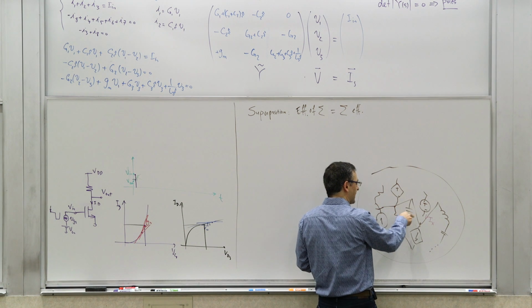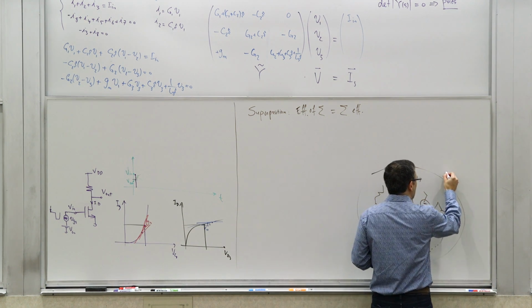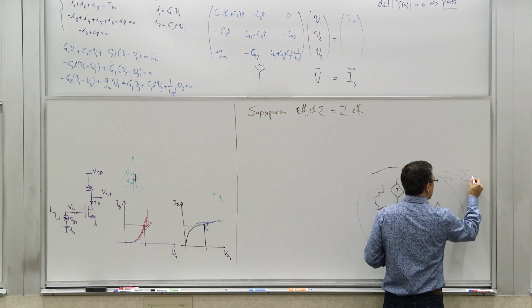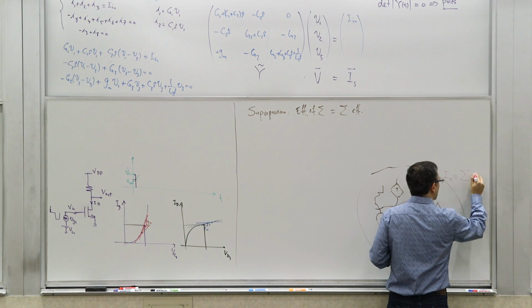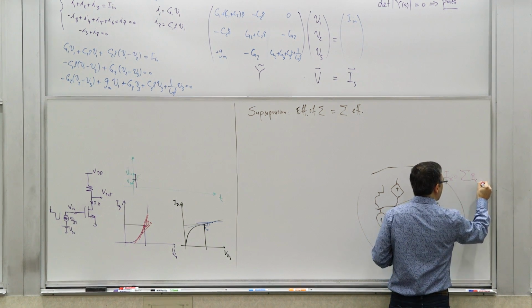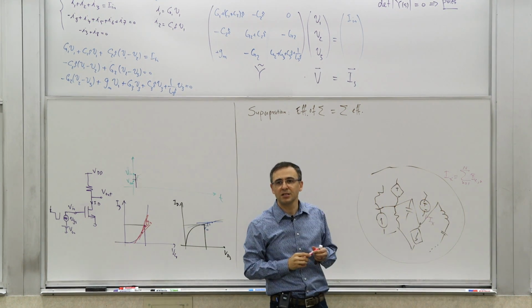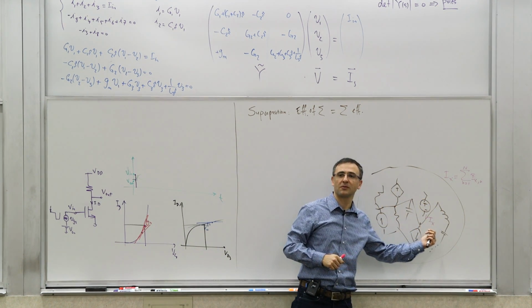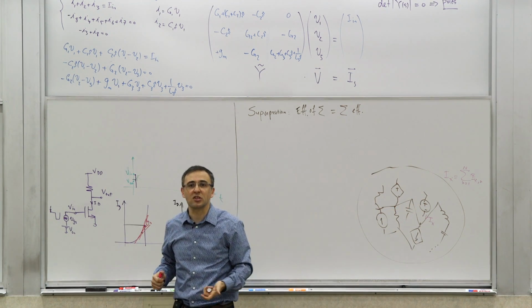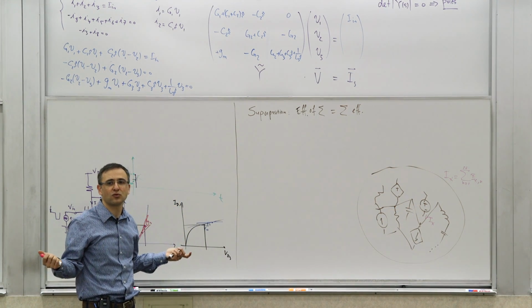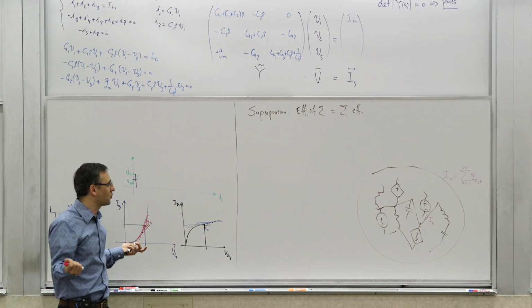And then you do it for the second one, you get Ix2. So then total Ix is going to be the sum of Ix_n, n equals 1 to capital N. So you calculate this Ix, and sometimes it may be positive. For some of them, it may be negative. You do an algebraic sum. That's the definition of superposition, how superposition works, right?